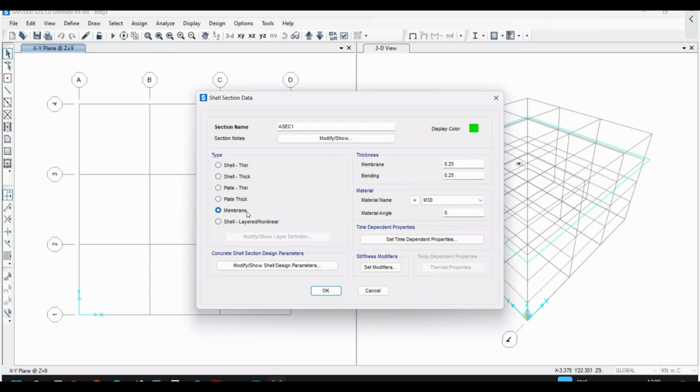So that can be other types of structures such as flat slab, where you need the out of plane bending of slabs. Then you can use shell thin in that case. You want to model the base or the raft or the foundation system. So in the previous example, we saw we assigned the fixed base to the columns, right? Pin type or fixed type.